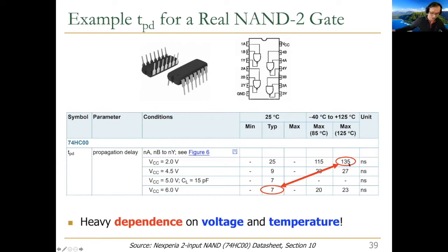So basically, typically, you get these propagation and contamination delays. In this case, contamination delay is not provided. Perhaps it's 0. I don't know. You have to look at other parts. Well, this is just the propagation delay, as you can see. Contamination delay, you need to look at some other row. Sorry about that. But you can see that even the propagation delay has a minimum and maximum.